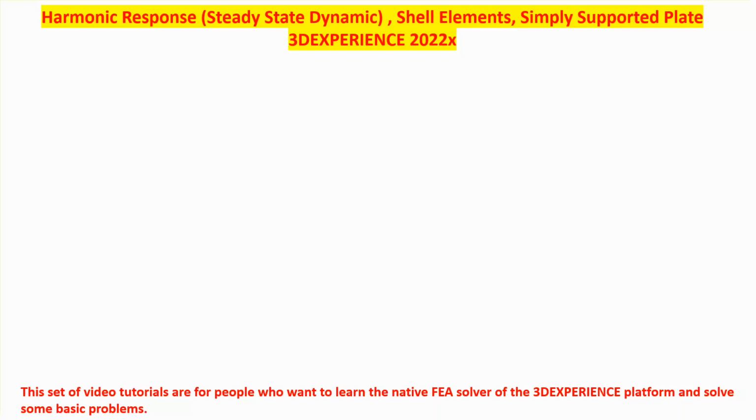Okay, the idea behind harmonic response is that you have an elastic object, obviously under small deformation, so it's really a linear problem. And we are interested in predicting the behavior of the structure when a sinusoidal load is applied, or sinusoidal displacement is applied at a particular node or a group of nodes.